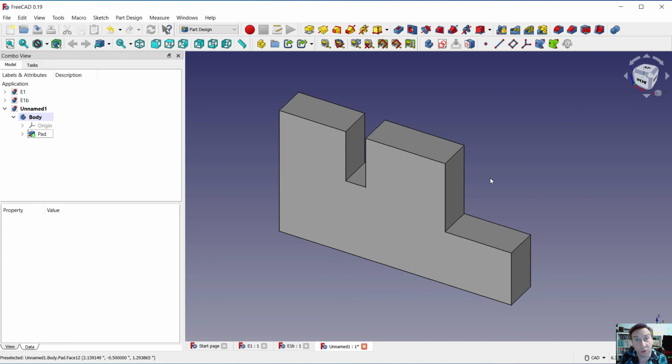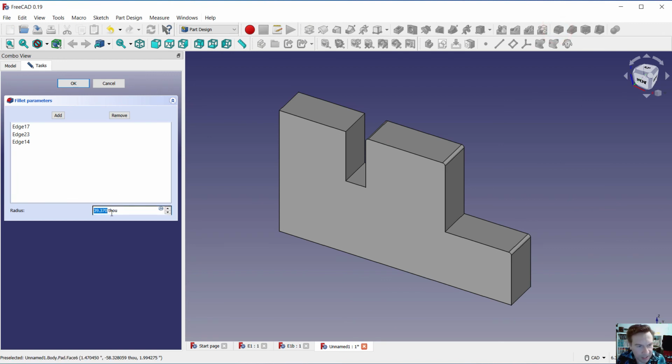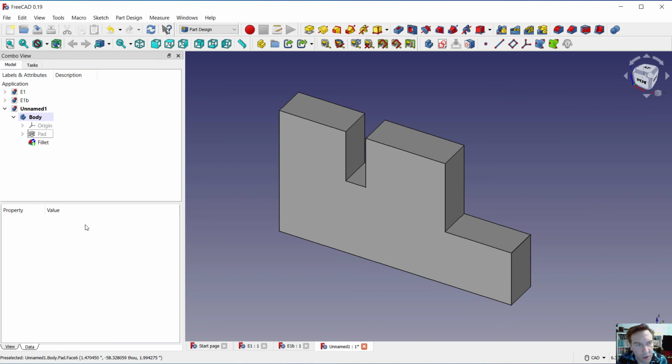Now, what I would recommend, if those of you who are just hobbyists, do whatever you want, but I would tinker with some of these settings. Remember, like, pre-select, like if you want to put fillets in, hold control and pre-select any areas. Like you can select, I can't get that little one in there very well, but let's go to fillet, and then again 1 inch. Oh, it didn't like that.